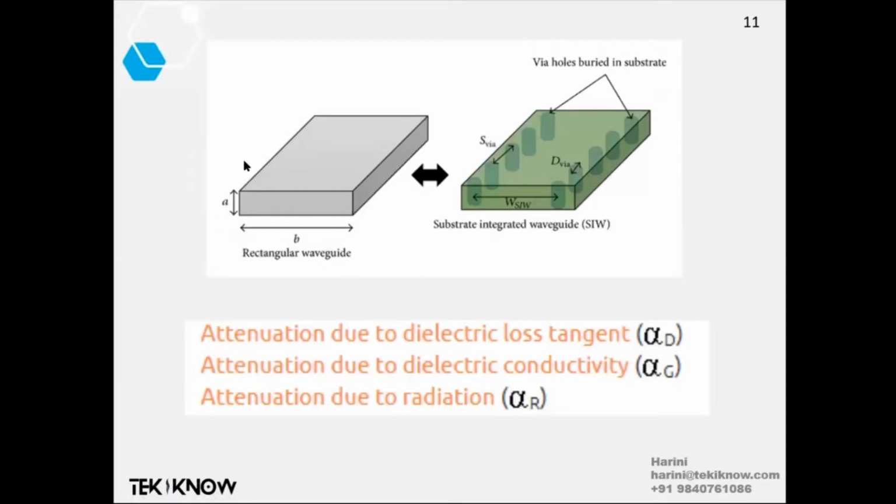You see, this is a rectangular waveguide, which is surrounded on four sides with metal walls. So to think about this substrate integrated waveguide, it consists simply of a ground plane, that is a conductor, which may be considered a wall, and the top layer also contains a wall. Then what about the sides?